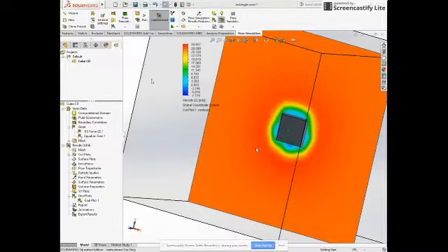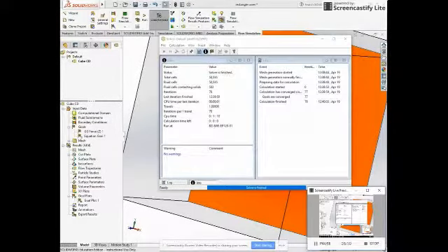That is pretty useful. So that's basically what you get out of running this analysis. When we performed the same analysis on the regular shell, it's still running, but we got a drag coefficient of 0.52. That is reduced by about 70% from the one we found on this cube, and that's a significant decrease.